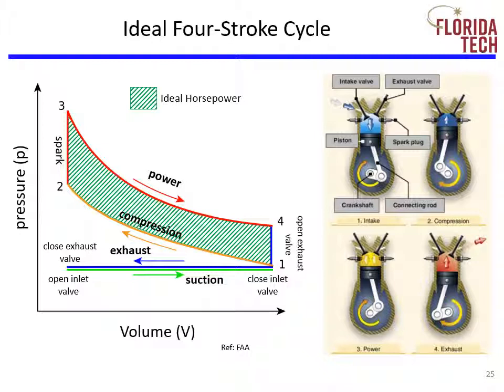Now, how do we get the fuel and air into the cylinders? Well, that's the induction system. Inside the cockpit of most general aviation aircraft, there are throttle and mixture controls. The throttle controls the amount of fuel and air that go into the cylinders, while the mixture controls how much fuel is mixed with the air. In simple terms, the mixture controls the ratio between fuel and air.